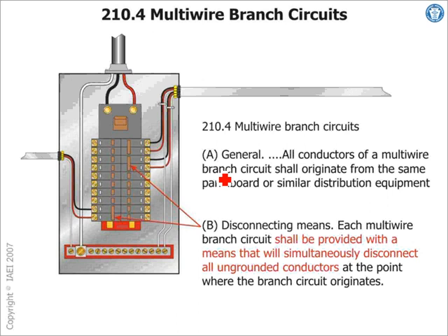If you have a multi-wire branch circuit coming in, you have to identify the neutral that goes with each multi-wire branch circuit, unless they are obviously or clearly obvious. For example, you have two cables coming in here. Every neutral in every cable is a multi-wire branch circuit. I have a conduit like this, and I have six conductors coming in, 2, 4, and 6. I can tell which neutral goes with which circuit. In a case like this, you have to identify them, group them together.